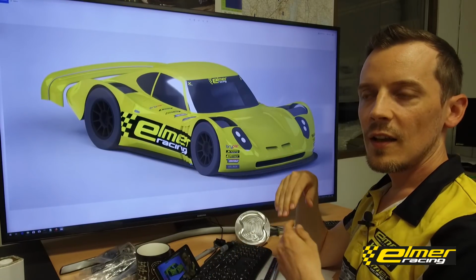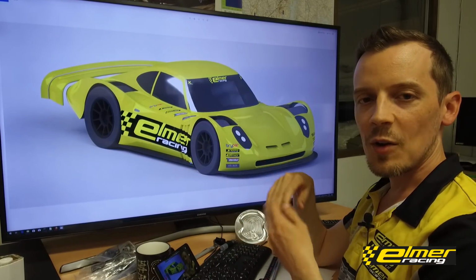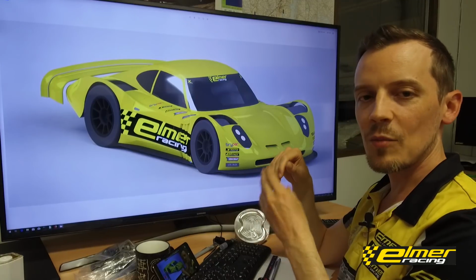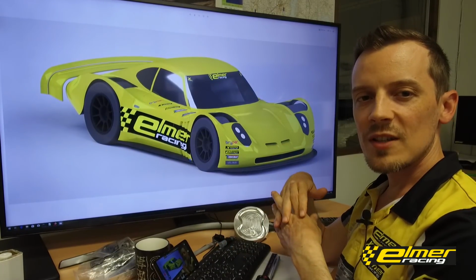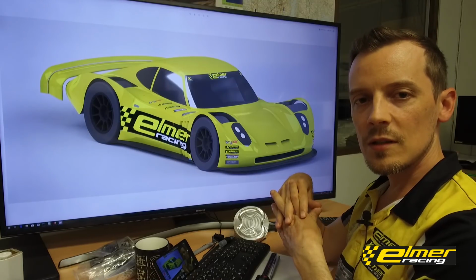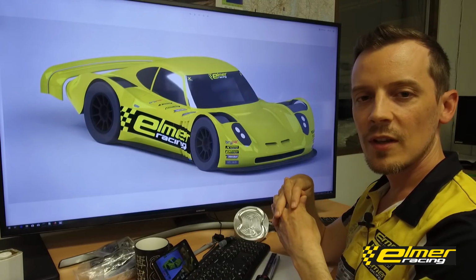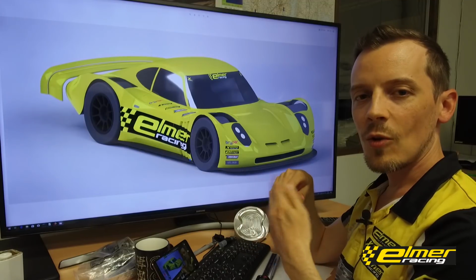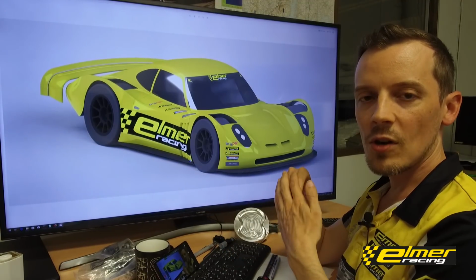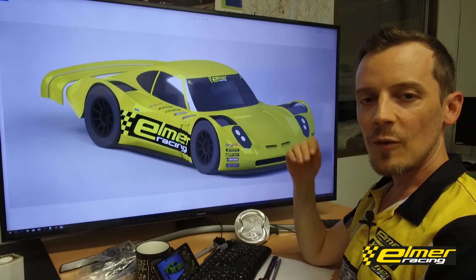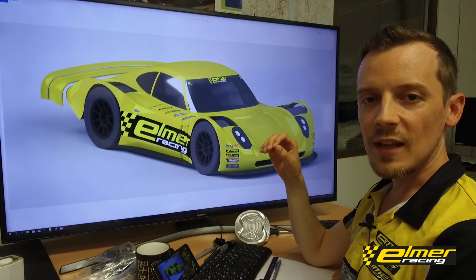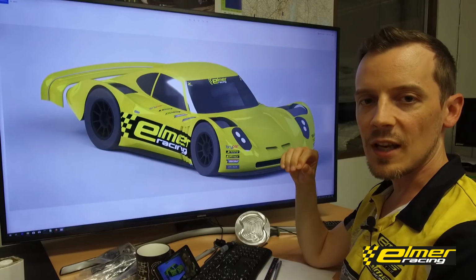Having gone through all of these variables and determined the mass of the brake discs we need, and optimizing the brake system with that, we basically have the weight as good as or even better than carbon brakes, but using much more affordable iron-based alloys for the brake discs.